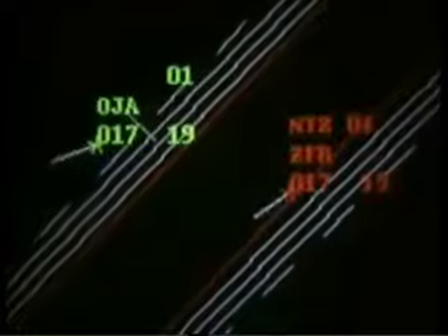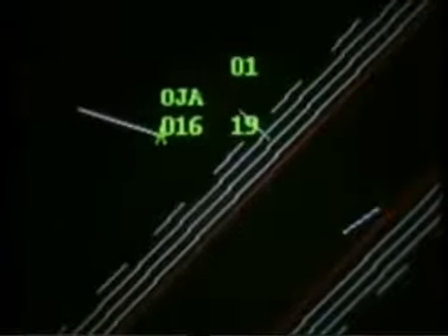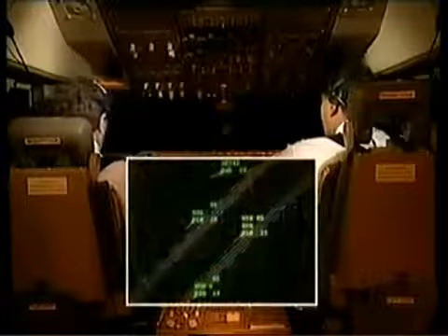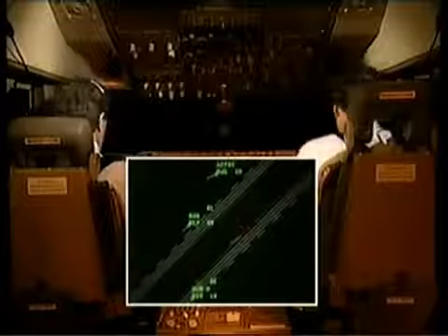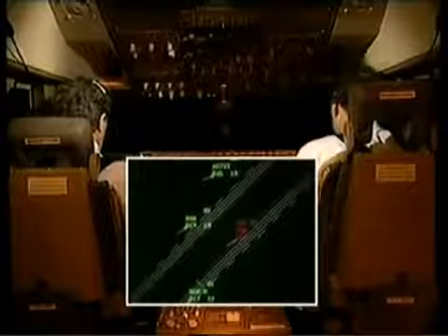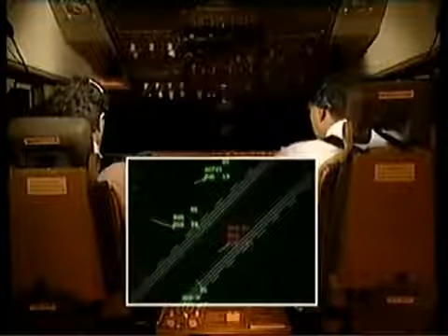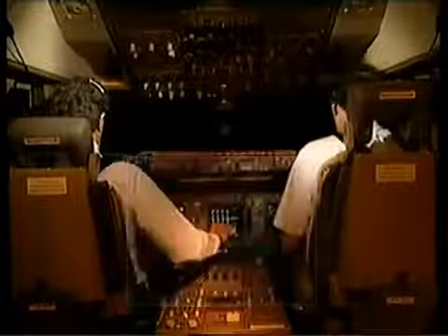The monitor controller must issue breakout instructions to any endangered aircraft on the adjacent approach course when an aircraft penetrates the NTZ. As you saw in the previous scene, a breakout is different to a missed approach because it occurs before an aircraft reaches the decision altitude, and more importantly requires a different set of procedures than the missed approach.